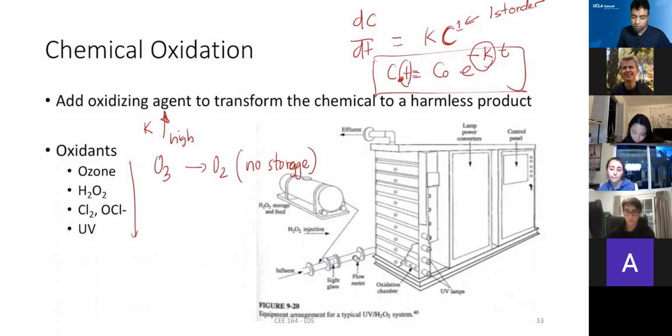And if you have too much other colored material, like organic carbons and particulates, the UV light will be blocked. So that's another ineffectiveness related to depth.